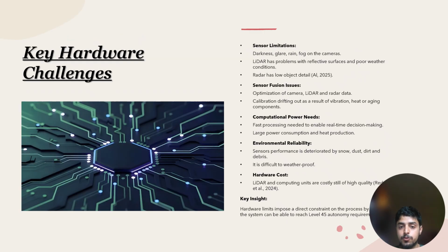Let's go to slide 4 about the hardware challenges. Self-driving car rely heavily on hardware such as camera, lidar, radar, and onboard computing units. One major challenge is sensory limitation. Camera struggle with the low light or glare. Lidar can be affected by weather and radar provide limited details. Another issue is sensor fusion.